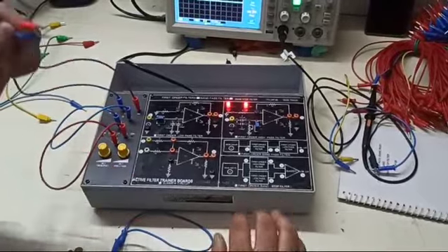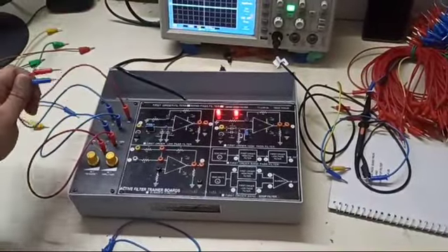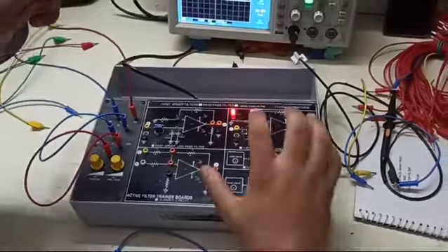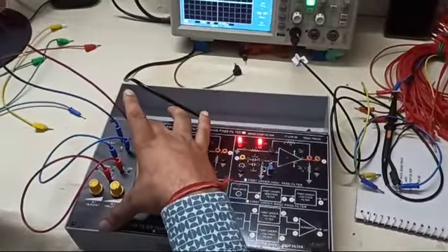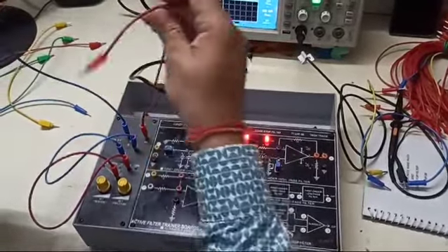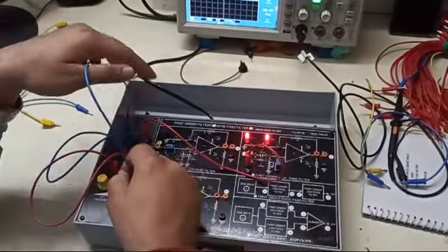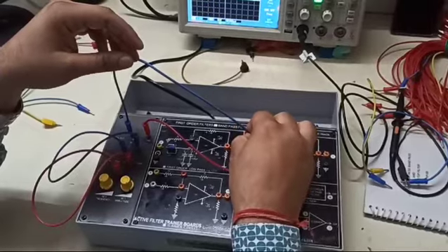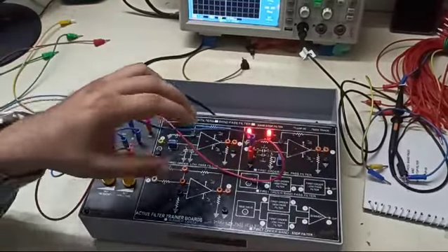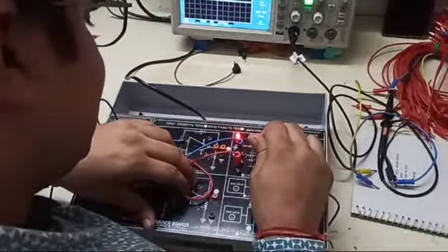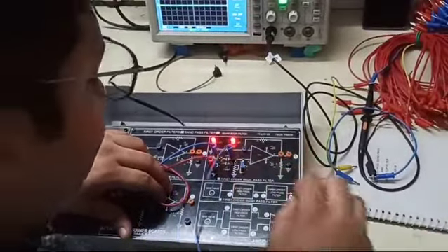Now we are going to go on with the high pass filter. In the high pass filter, we will use the same function generator as input. We will connect the ground to ground. We will connect the output of the function generator to point C, and we will select our capacitor. Right now we are selecting 0.1 microfarad,